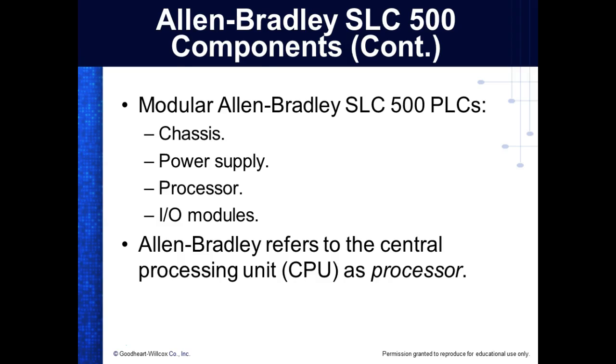Now we don't have very many I/O modules. And this is what we try to specify because we call them I/O, even though odds are they're either what? Input or output. Y'all understand that? A lot of our communication modules are true I/O modules. But we call these I/O devices, even though they're predominantly just input or output. So this module right here has 16. It's a 16-bit input module, and this right here is a 16-bit output. Y'all understand that term now, right?